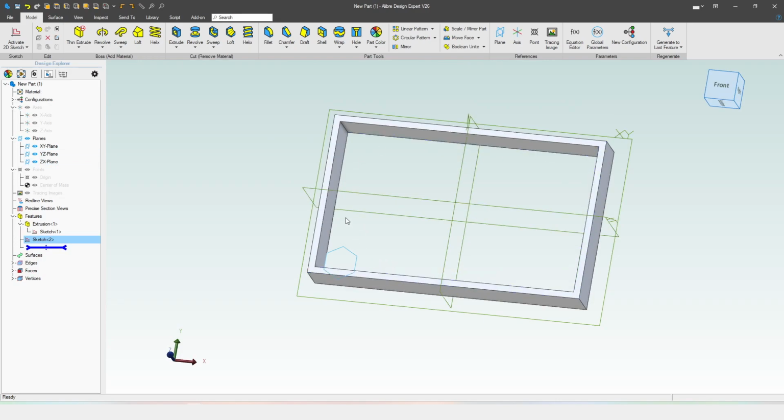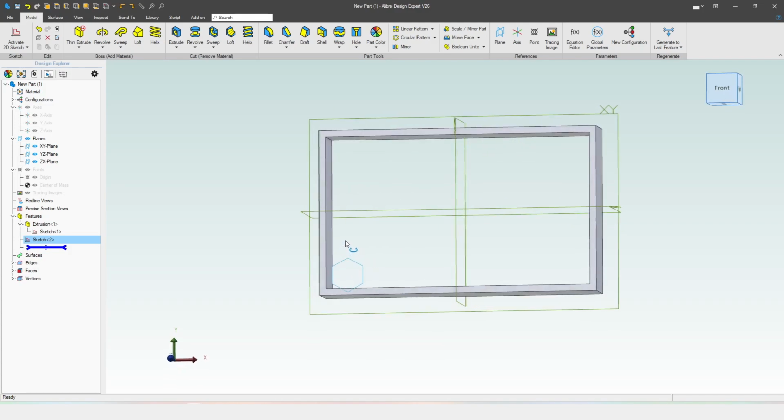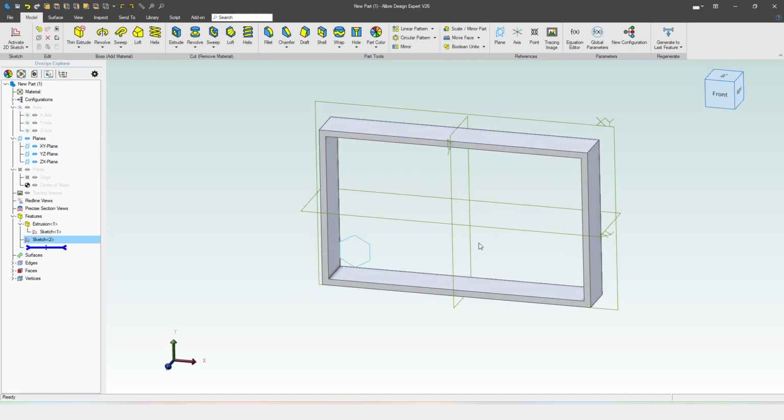this entire internal area is going to be filled by a hexagon that follows that choice I made. Okay, so if you choose the number of instances along one direction, and because a honeycomb is made up by hexagonal structures that share their sides with the neighboring hexagons, that means that the number of rows of such hexagons is then going to be a calculated value. So if I choose the number in one direction, the other one is a fixed calculated value, okay? In order to fill an area, that is.